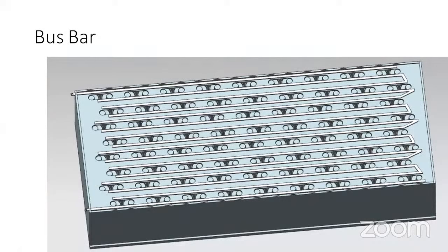What is that? Encapsulant, or you can say potting material, is thermally very insulative, and electrically also it is very dielectric. So that acts as a barrier between two cells and separates them. Once any cell achieves the thermal runaway event, the heat and all should not get transferred or propagate to other cells.